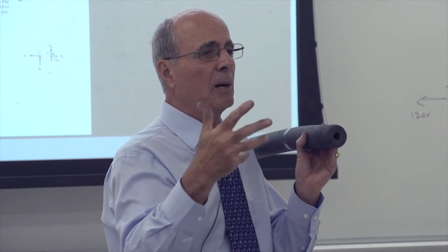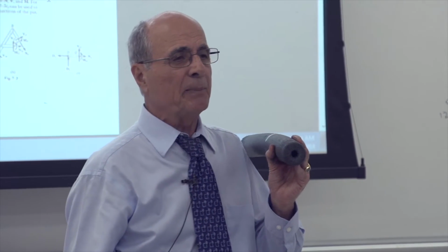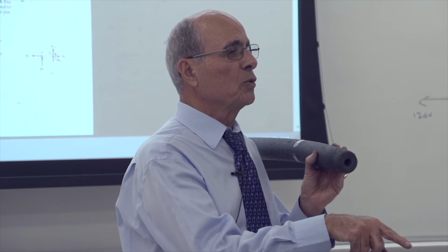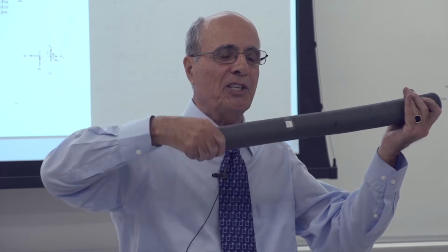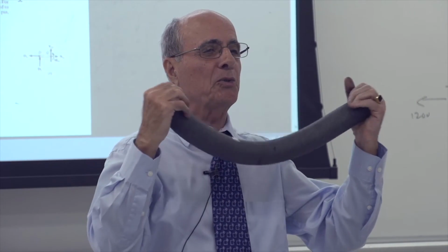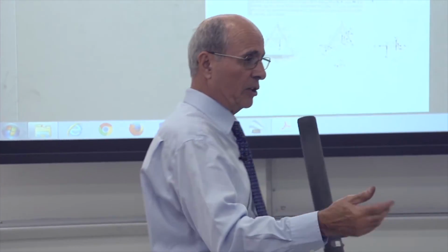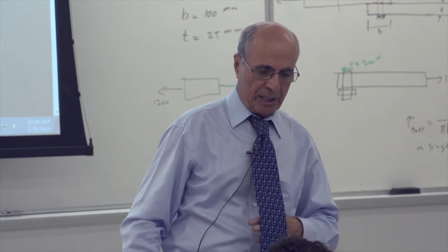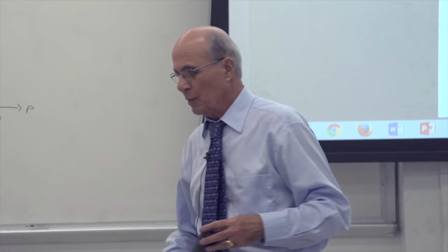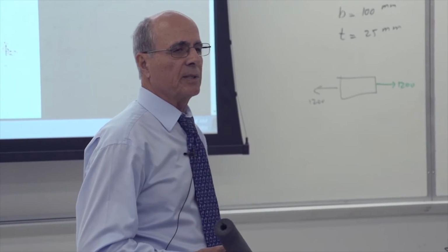Then you have one M here, one vector M. That vector M has 3 components, Mx, My, and Mz. One of them is not normal anymore. We don't call it normal. Look at the picture. One is this action. This is torsion. The other 2 are bending. These are the discussions we are going to have in the next few weeks. Everybody understand what happened to this object? However, write it down if you want to write it down. Internally, when we have a force, one component will be normal force, the other 2 will be shear forces.